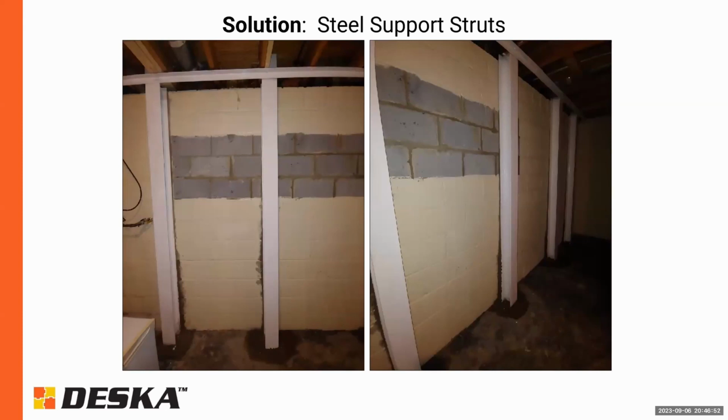They have footings down below the slab that they are essentially poured around, as well as, in this case, a steel angle that attaches to all the floor joists above. And then the space in between the steel beam and the wall is grouted, because the wall is typically bowed inward in some way. The steel beam is perfectly straight. So, usually closer to the top and the bottom, there's a space, could be a quarter inch, could be 2 inches, could be closer to 3 inches. That gets filled with a grout so that the steel beam provides an evenly distributed load on the wall.